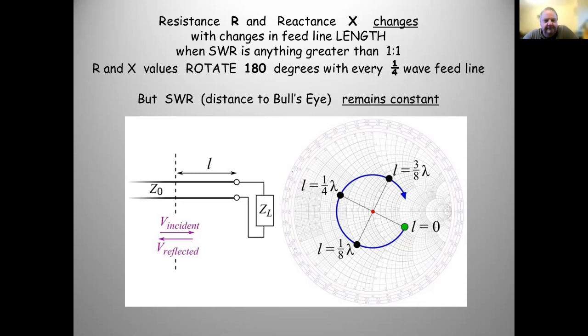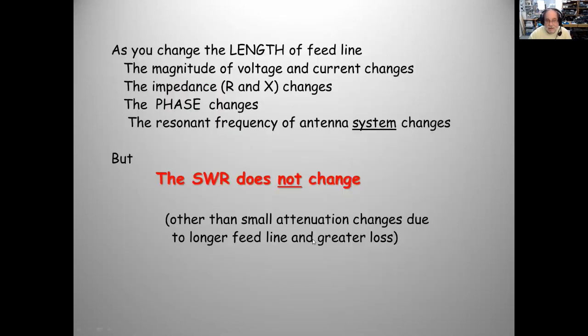Yes. So often we think, well, how can I improve the SWR? Could I improve the SWR by adding a little extra coax or cutting some off? No. Unless the coax is radiating, I suppose. Oh, well, yeah, that's true. I'm assuming the shield isn't part of the antenna. Let me see what else I've got, but let me skip a couple.